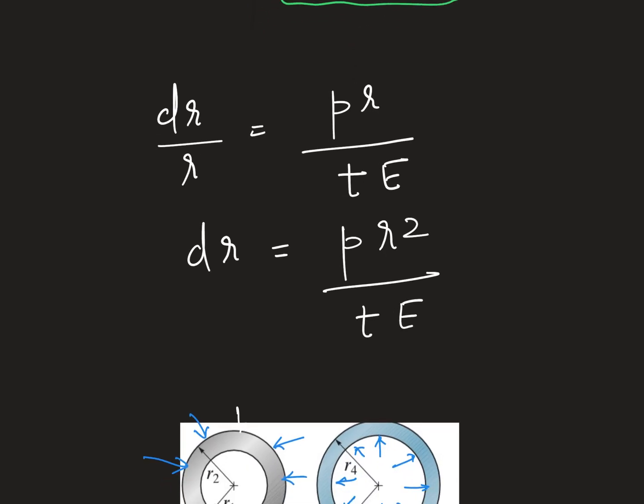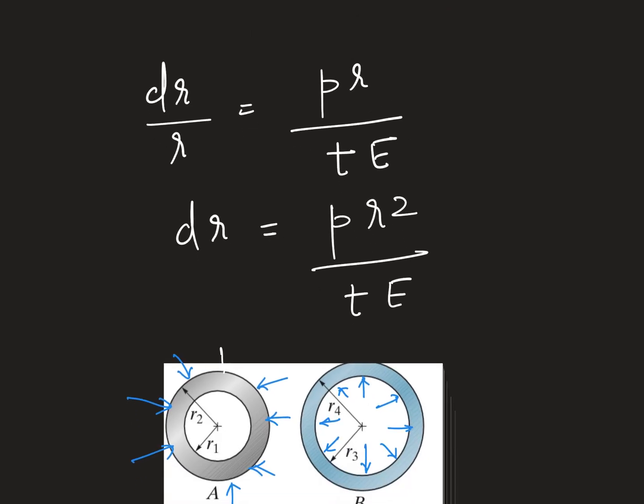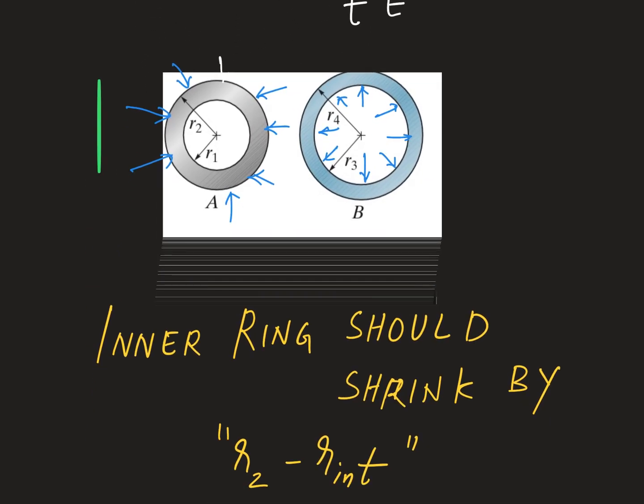Now the rest of the things are simply plug and chug. Now this expression gives you, for a given internal pressure, Young's modulus and thickness of the ring, what is the delta radial movement that my ring will have. Make sense? Clear? Okay. Now, having seen this formula and its utility, we can go ahead and use this formula to solve our problem, because conceptually we have put everything into buckets. Now it's just a matter of clubbing them.